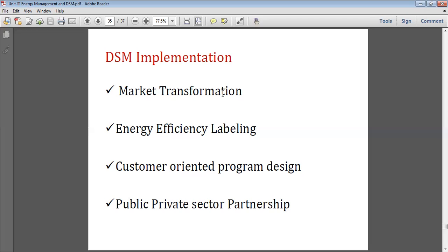Now, what is the advantage? It gives more light. The advantage is that if you are going to install, say, 20 lamps, now only 16 lamps are sufficient to install in the hall. Suppose you have a small factory shed and you design it with regular lamps, 20 numbers. But if you use the energy efficient lamp, you can increase the distance between two lamps. You can increase the height of the lamp as per the application, and you will still find proper lumens reaching the floor.